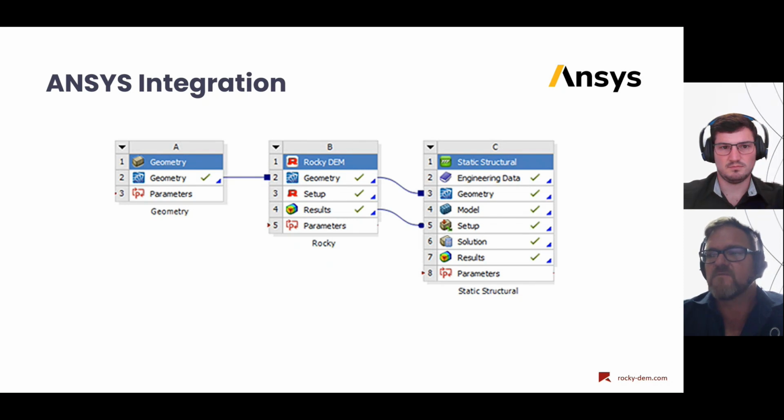There's several strongly coupled simulations where it will solve the iteration DEM and an iteration CFD, which is very beneficial because you can solve the CFD iteration on the CPU and the DEM iteration on the GPU, and you'll get a very efficient simulation.